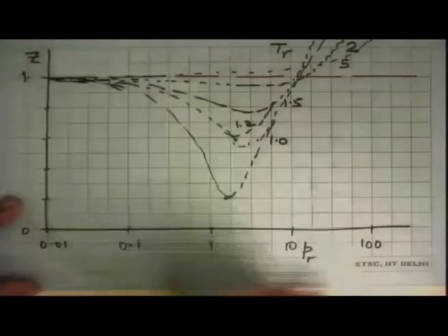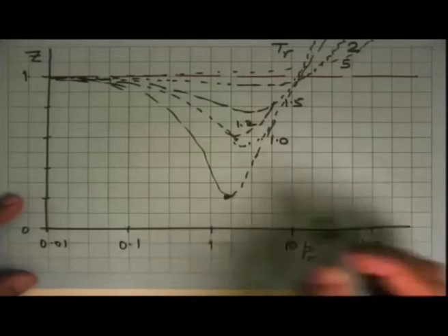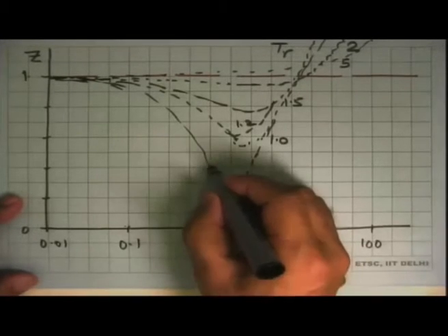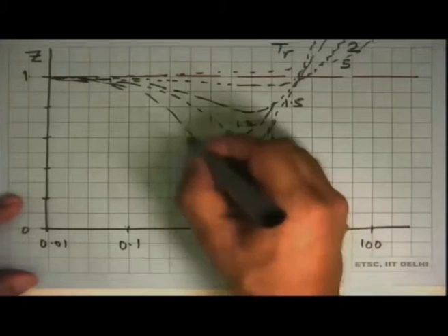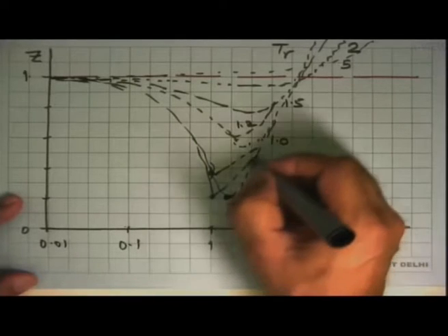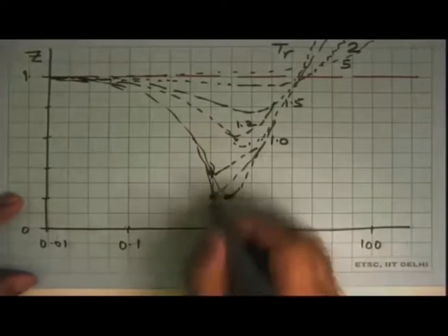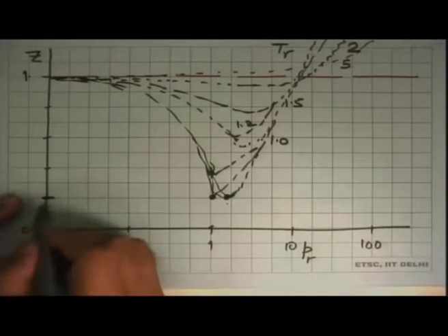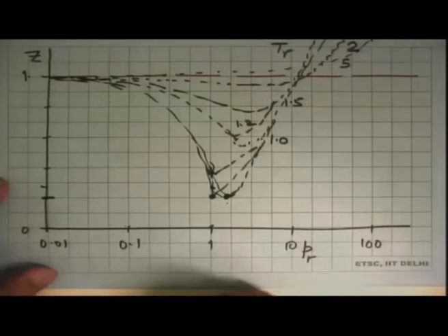And below that, you have a curve. So this will happen when it is 1. Sorry, so this line should be like this, 1 and 2, so somewhere here. So reduced pressure is 1, reduced temperature is 1, and you get Z critical, something like 0.27 or something like that.